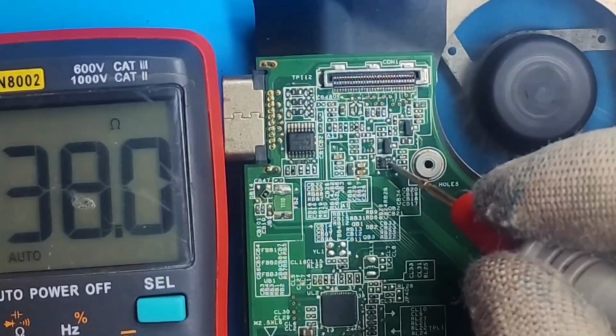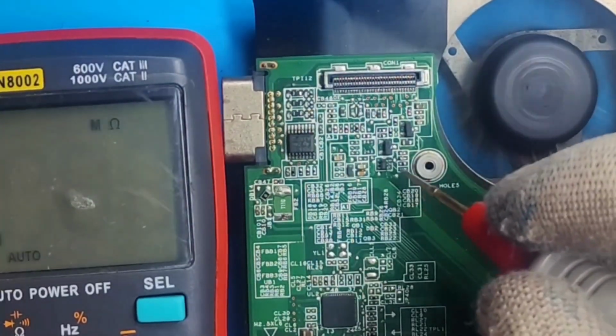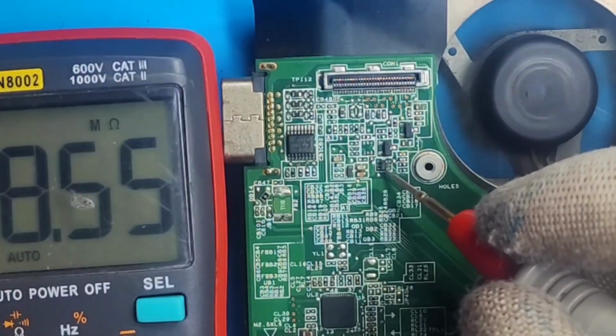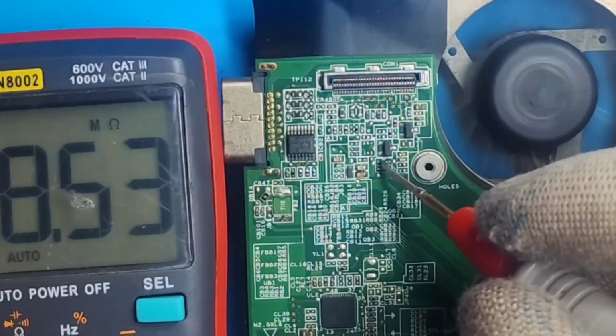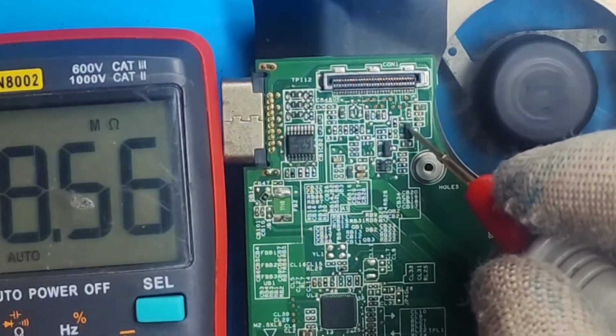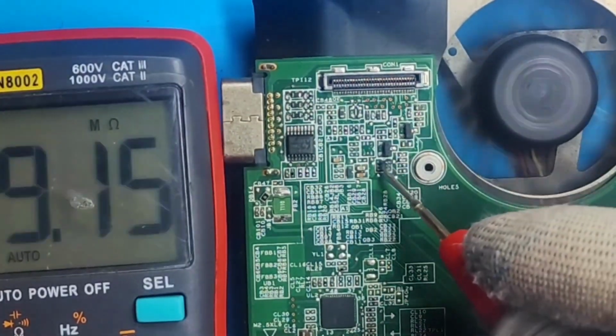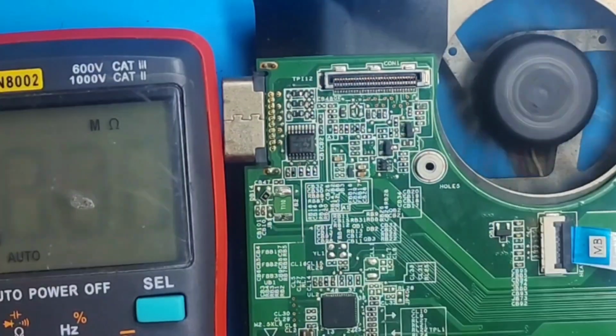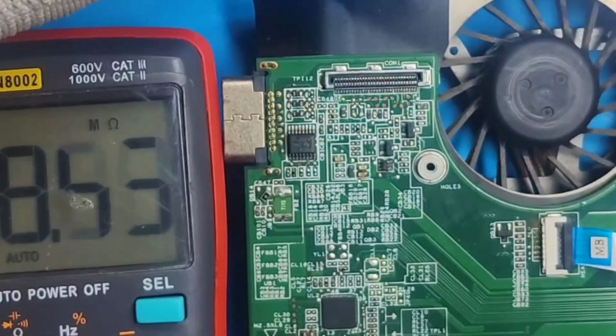it will not conduct. So we need to remove this MOSFET and connect the source, I mean the ground, and the drain point of this MOSFET, so that we will be getting ground for this MOSFET here. Unless we do this type of work, we can't solve this problem in this motherboard, because there's a problem inside the PCH which is unsolvable. So this is a tricky way.